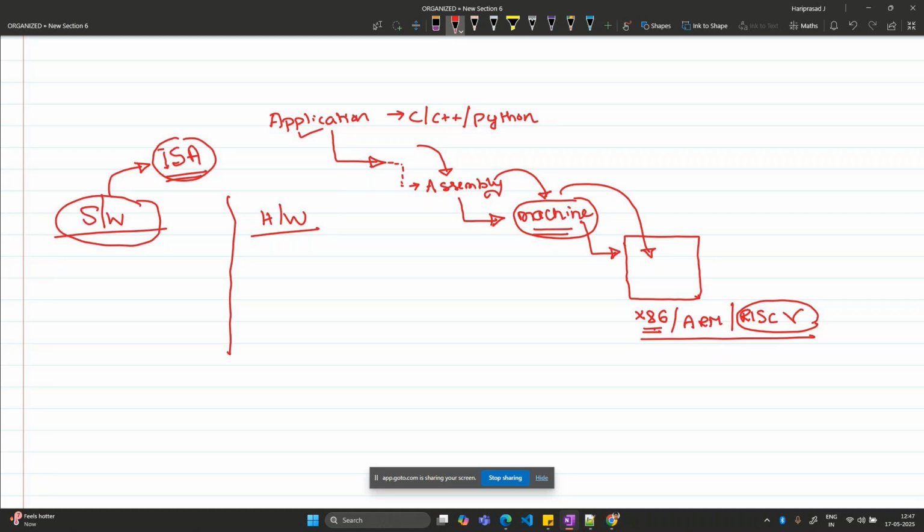Those of you in verification might know how we usually verify. We have one golden model, and we also have some designed hardware. We generate certain test vectors from the golden model, feed them into our design and test, and we get some output, and again we have to compare that output with the golden model. That is how we actually verify it.